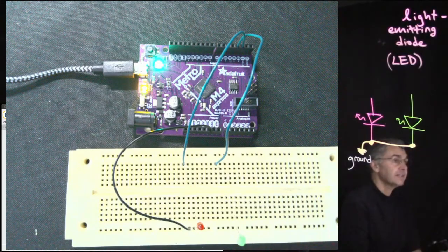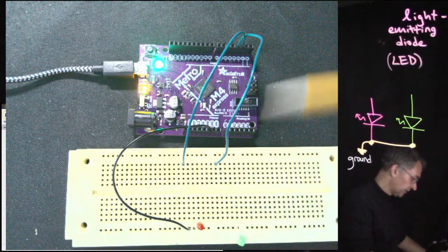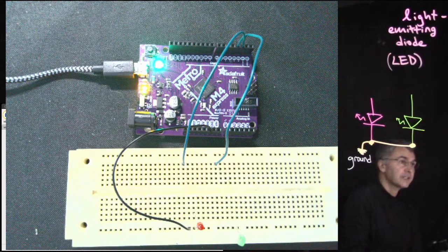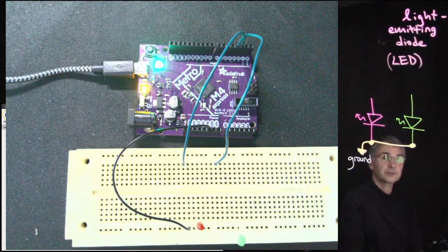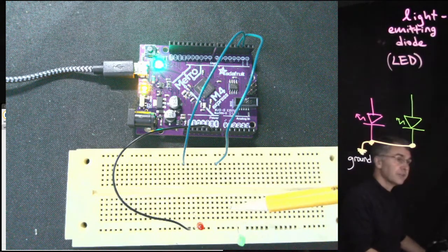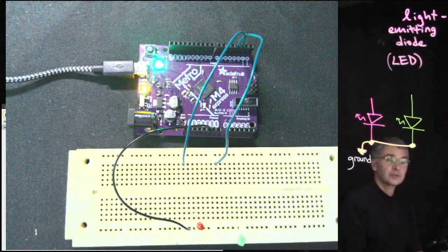And you could say, why didn't I connect these LEDs' positive sides directly to pin 2 and pin 3? Well, to make an LED light up, you want sort of tens of milliamps of current to flow through. In general, if you put a DC voltage directly across the 2 leads of the diode, a large current will flow and you can burn out the diode or LED.